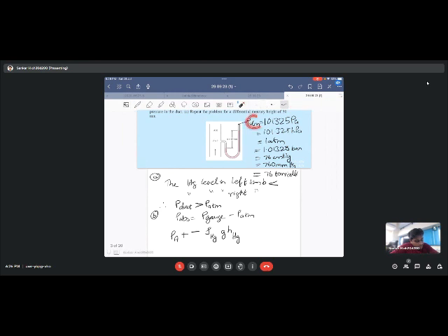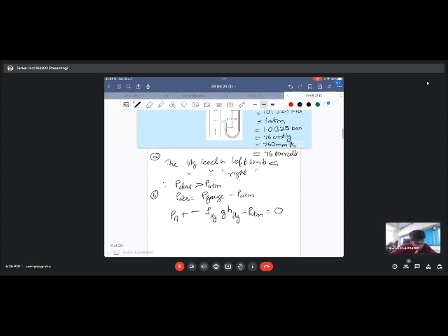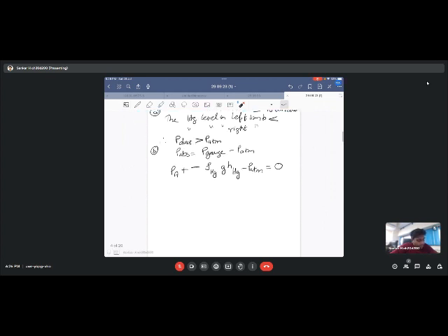And we know that this pressure over here is acting in this direction, that's in the opposite direction, and therefore PATM, and we equate that to 0 over here. And this pressure as rho gh is explained well in the lectures by Professor Sumesh. And from here we can easily find out what the value of PA is.